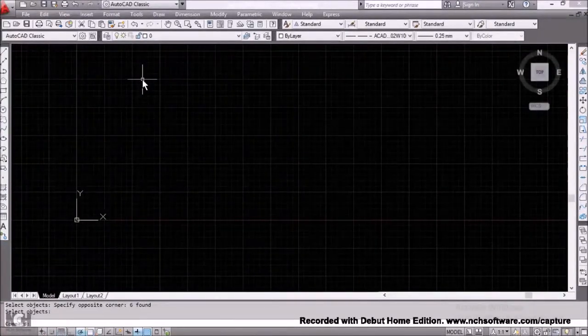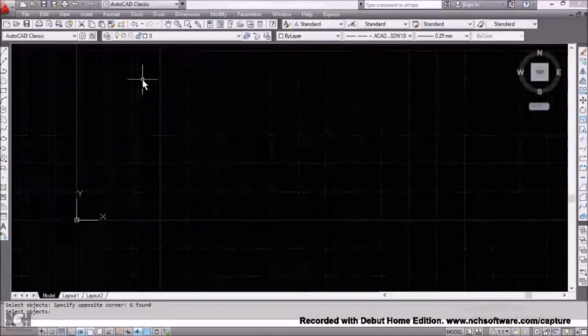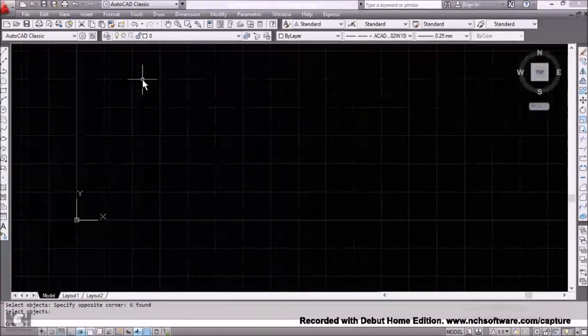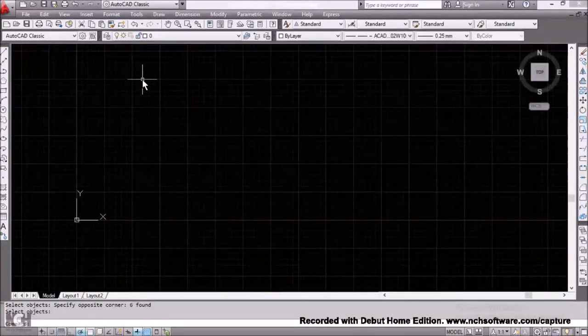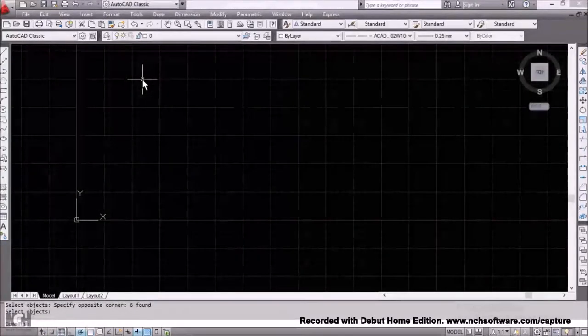The reason for this method is if you want to locate a particular point using the AutoCAD software, and you want the point to make reference to the origin, so you use the absolute coordinate method. You want a particular point to make reference to the origin of your interface, so you use this method.